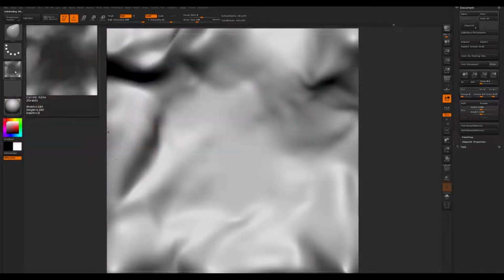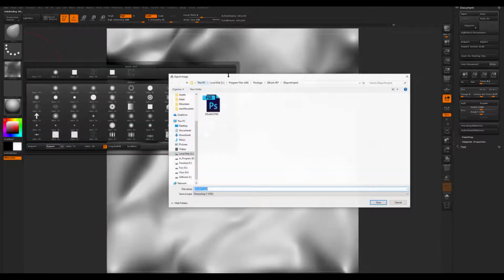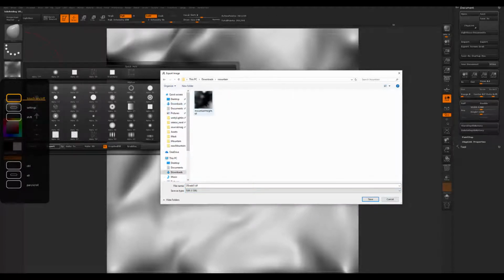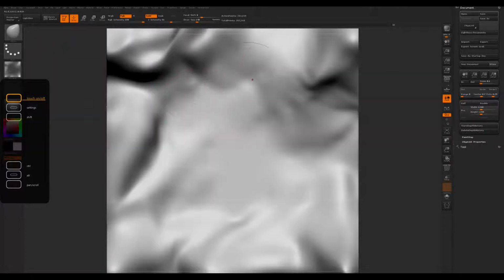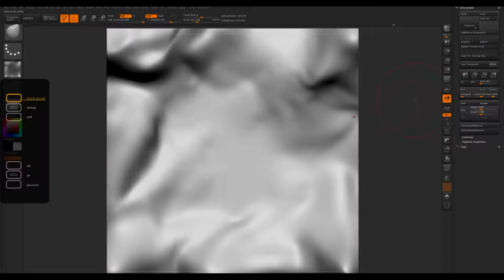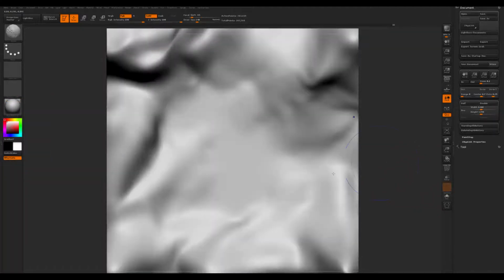Okay. Anyway, but after that, all you have to do is go alpha and then grab it as an alpha, and then export it. Okay. Let's change the format into TIFF and then save it somewhere. I'm gonna just save it here and then save to replace the one I had earlier. It's gonna be a heightmap, and we can use that heightmap directly in Game Engine or other packages. So that's the first step in ZBrush. The goal here is lay out the mountain, and I think the most efficient and totally in control way is using ZBrush.